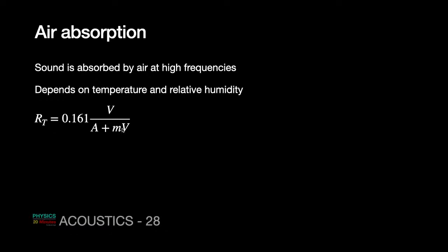If you have to maintain the reverberation time in seconds, then this has to be dimensionless. Therefore, since V has the dimensions of meter cube, M has to have the dimension of per meter cube. So basically, how much sound is absorbed by air is specified per meter cube.